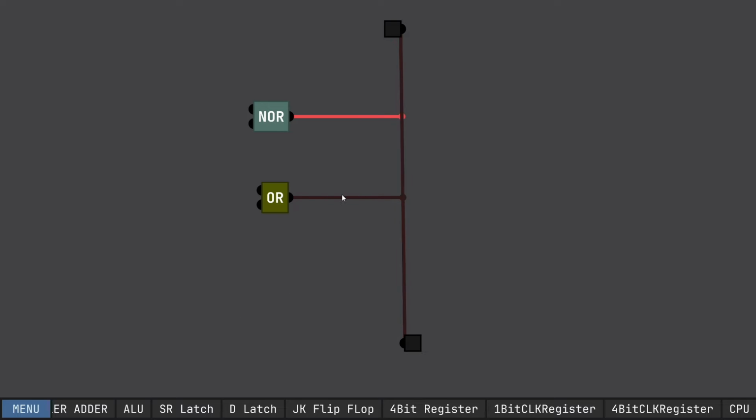So we need a way to determine what data gets put on the bus, and then for all the other registers to emit virtually nothing. It's not a 0 or a 1, it's nothing. It's no electrical communication at all to the original component. In the simulation, it's represented by being black. So a 0 in the simulation is actually this dark gray color, and then nothing is a black color. So if something is a black color, we say it's floating because we don't know what it is. We don't know if it's a 1 or a 0. It's black. There's no connection. It's floating.